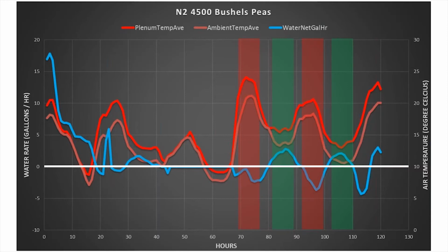you can maybe, by cooling it, maybe you'll have enough BTUs in that grain mass to get your grain dried. But if you have 4 points or 5 points of drying to do, there's no chance that you're going to have enough BTUs in your grain mass to evaporate all your water. So to just cool the grain and just run your fans at night is going to result in a really cold bin of very tough grain.